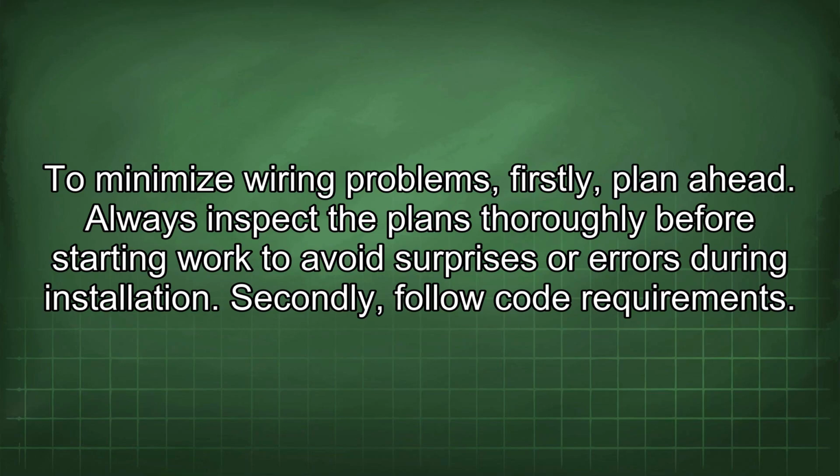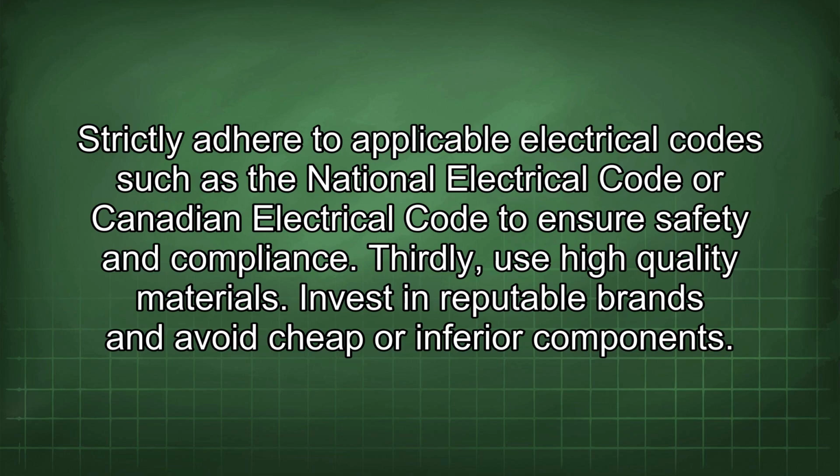To minimize wiring problems, firstly, plan ahead. Always inspect the plans thoroughly before starting work to avoid surprises or errors during installation. Secondly, follow code requirements. Strictly adhere to applicable electrical codes such as the National Electrical Code or Canadian Electrical Code to ensure safety and compliance.